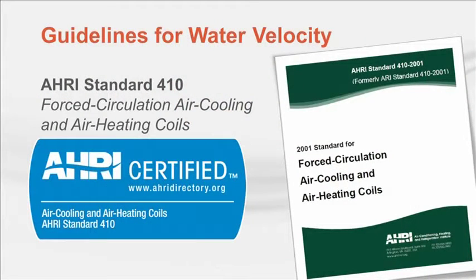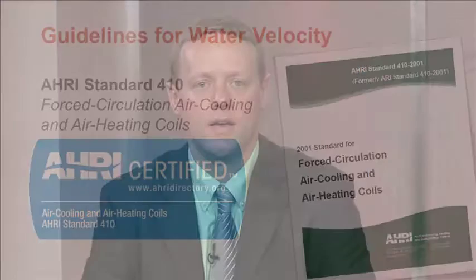Most coil manufacturers rate and certify their performance selection programs using AHRI Standard 410. This standard establishes a single set of testing and rating requirements for determining capacity, as well as air and water pressure drops for cooling and heating coils. This provides design engineers with an apples-to-apples comparison of coil performance from manufacturer to manufacturer.